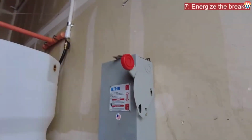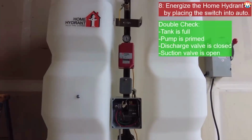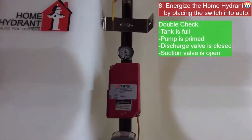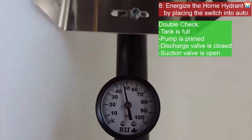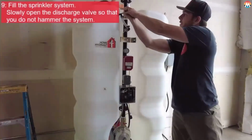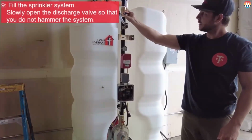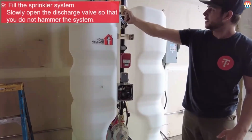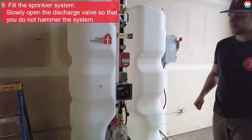Now energize the panel. Flip the switch from off into auto. This will start the pump and start the timer. The pump will run at churn, which is 47 psi on this model. Now is a good time to fill your sprinkler system. We start the pump with the main discharge valve closed and then open it slowly so as to not hammer the system with 47 psi.